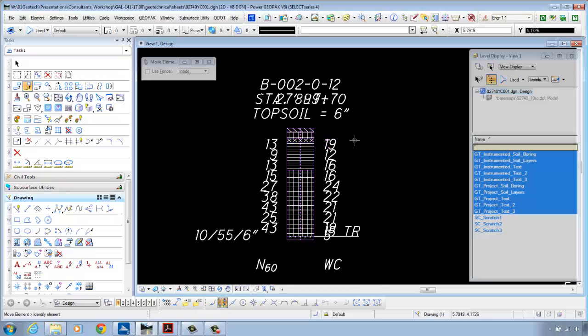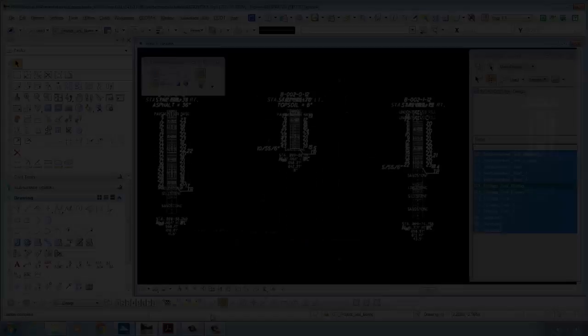If you use the simple fence report and you have samples that need notes beside them, then you're still responsible for adding those notes for uncontrolled fill, organic soils, cobbles and boulders encountered. Anything that you would want noted on the side of the boring graphic, you're responsible for adding that. So I'm going to go ahead and clean up all the rest of my overdrafting right now, and then I'm going to come back.